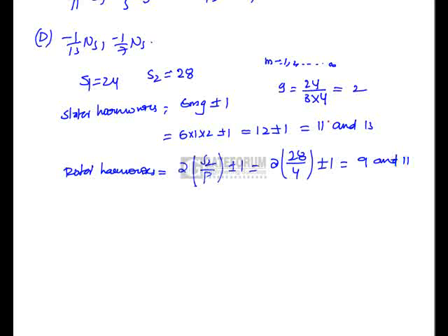Now if you see stator and rotor, the 11th harmonic is the common harmonic. The dominant harmonic in stator is 11, whereas in rotor it is 9. The common harmonic is 11, so the speed corresponding to synchronization is due to the 11th harmonic. Now what is the speed due to the 11th harmonic?